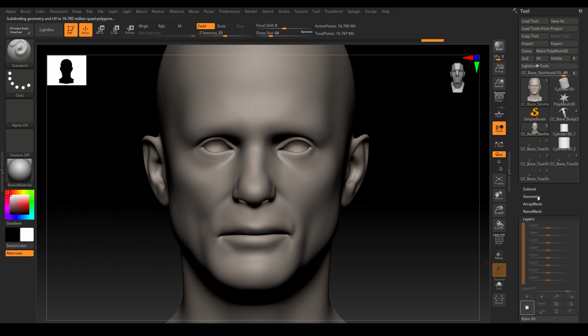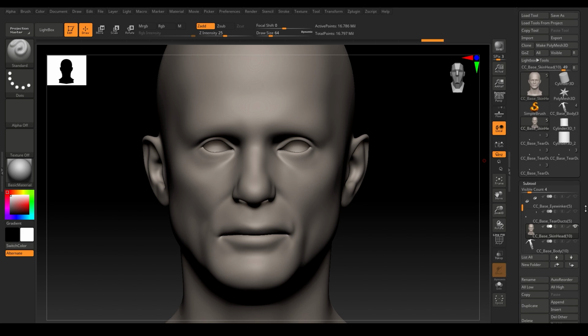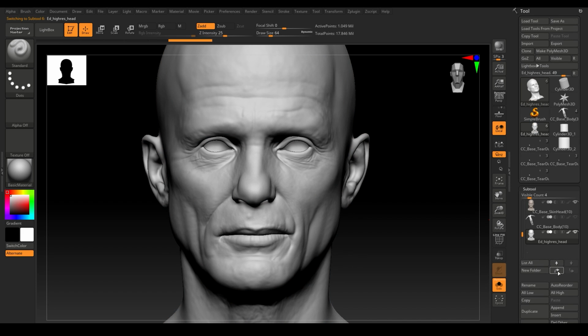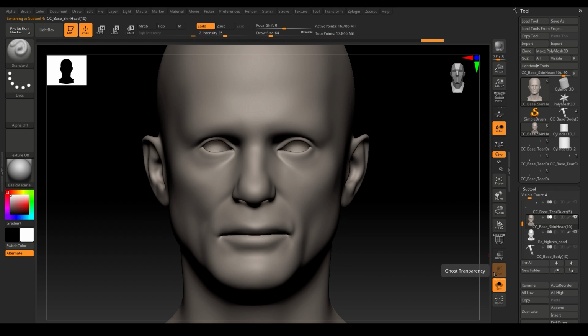And I'm going to make a new layer. And then now I'm going to bring in my previous sculpt, so the level 5 sculpt, so I can project. Okay, so I've just appended my head here. And what I'm going to do is project. So make sure all the other subtools are turned off, just the 2 heads showing. Select your new head here.